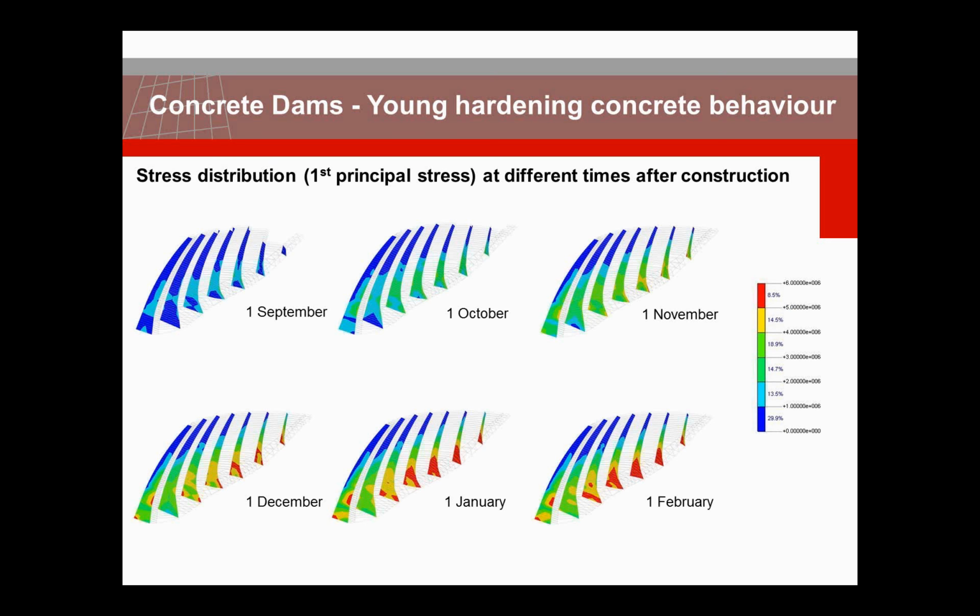And then after this heat phase, we can calculate for every time step also the principal stresses based on this linear analysis, which you see here, same time color scale, varying from very low level stresses to tensile stresses up to 6 megapascal, in the second half of the construction phase of the dam until some months after.